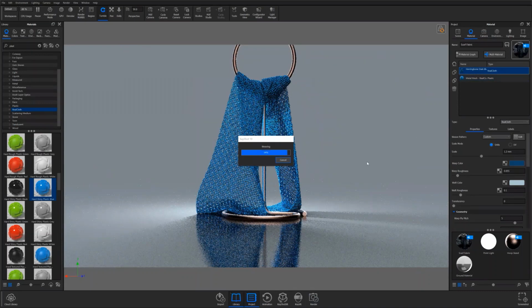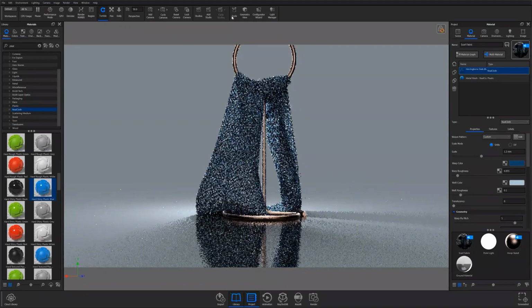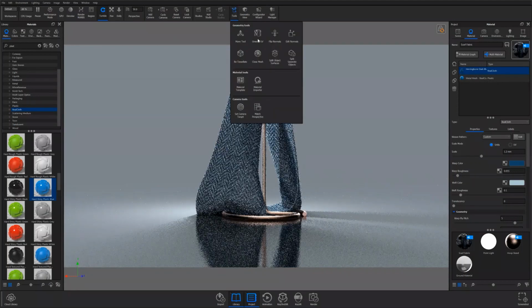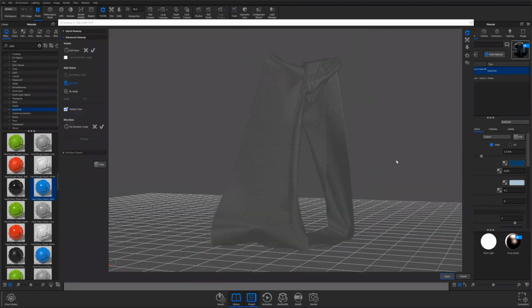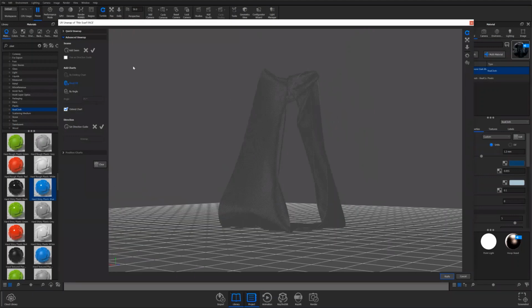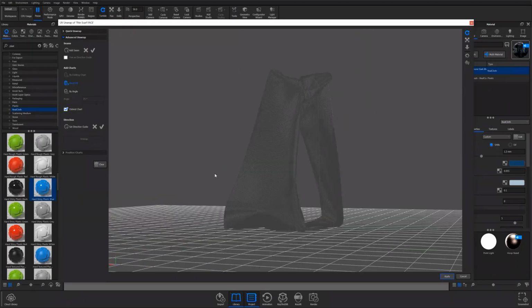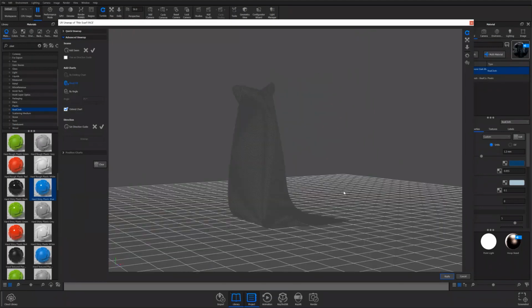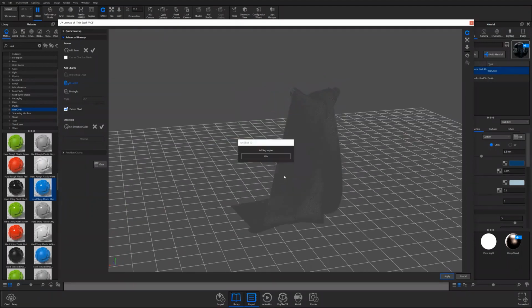Does KeyShot have a UV option now as well? Yeah, if you can go up to the tools menu. As Kareem mentioned, with smart export, you need UV unwrapping for things like USDZ export. So within smart export, we've made it so that you automatically UV unwrap and bake as part of the export process. Inside of the tools view, you can also do manual UV unwrapping.